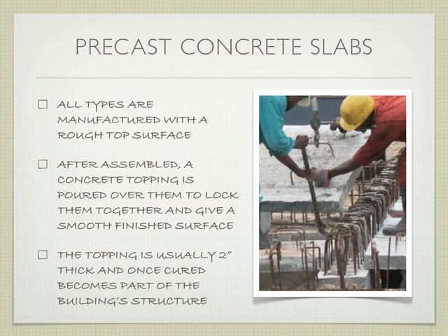So they're providing structural strength. The topping just ties them together. The topping's usually going to be about 2 inches thick, and once it's cured, it becomes part of the overall building structure.